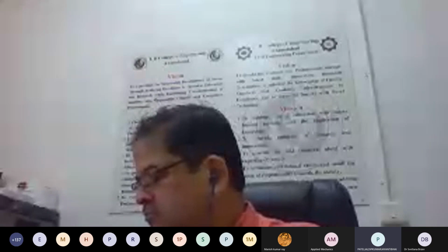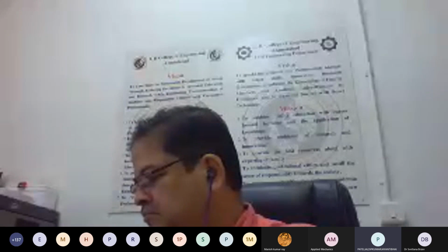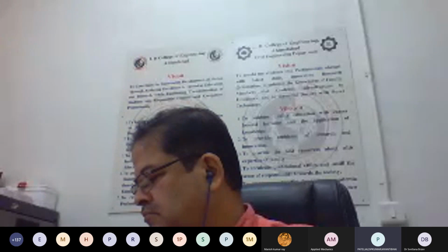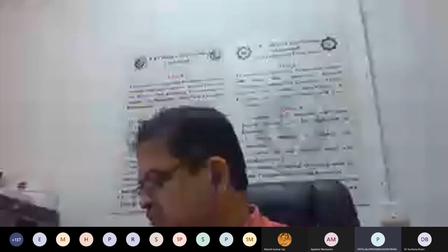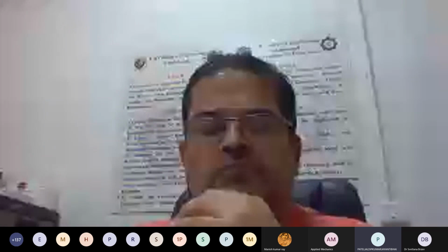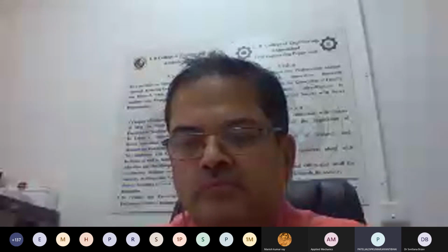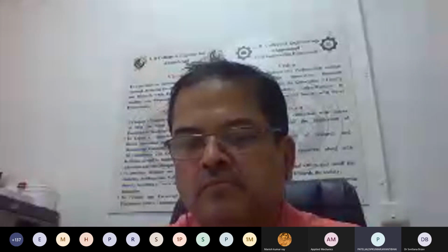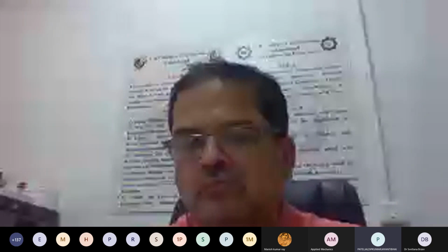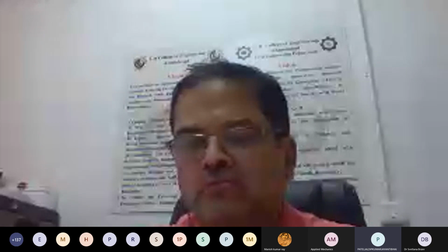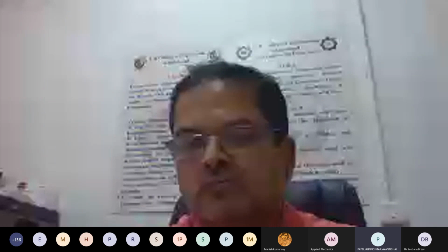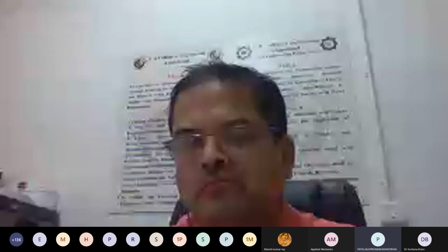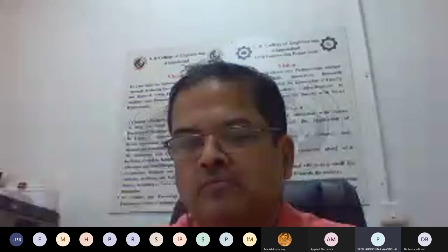In IIT Gandhinagar, the foundation was fully in masonry, and as I said, it is illustrated in that publication, which is free of charge, so you can see the section of the wall. The reinforcement in tie column was anchored into the plinth band, which was made deeper than usual. So the depth or height of the plinth band was, I don't recall, maybe 350 millimeters or more, so that the reinforcement would be properly anchored into that. So there are two options. In any case, foundations are wall foundations or strip foundations.